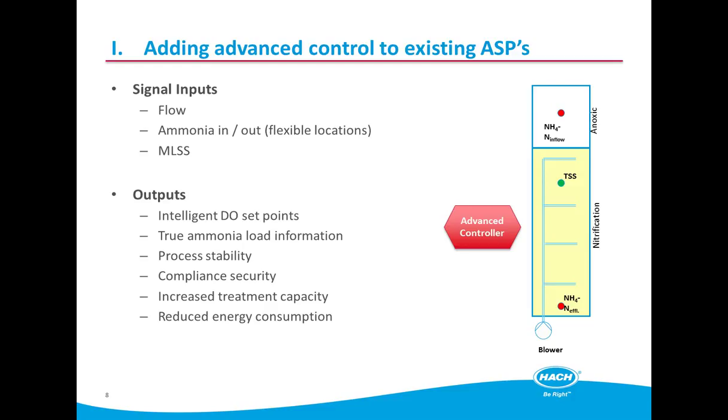So you have a sludge age that's far too high, a lot of bugs that are just sat there with endogenous respiration, not doing a great deal of treatment, but grabbing the oxygen before the delicate nitrifiers can actually utilize it. In those cases, a sludge age controller would really help, because you know that you're providing the right balance of both carbonaceous and nitrifying bacteria, and you're not generating additional biology that doesn't contribute greatly to your overall level of treatment.